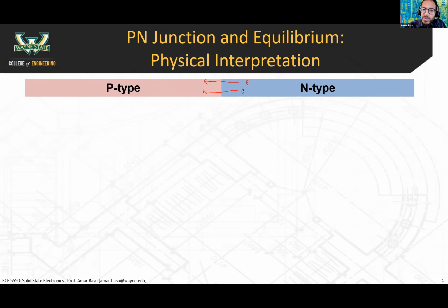Why do they diffuse? Because remember, diffusion goes from high concentration to low concentration. An n-type material has high electron concentration, and p-type material has very low electron concentration, so the electrons will diffuse from high to low concentration. Similarly with the holes from the p-type to n-type. So that's why, as Melvin said, it sets up this sort of crisscross type thing.